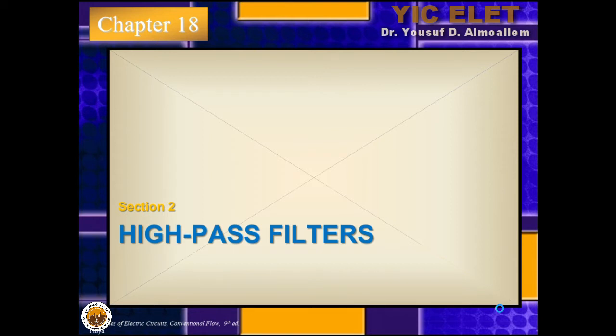As we saw in the low pass filters, the position at which the capacitors or inductors are placed changes the function of the filter. So we can use L or C to make a low pass filter, and you will see here that just changing these positions will change the low pass filter to a high pass filter.